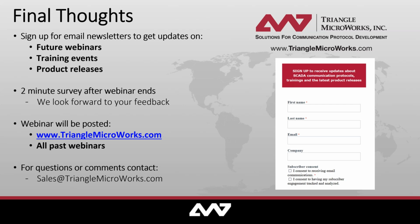Okay, next question. I will just throw out to both of you. Is GOOSE limited to binary values? No, absolutely not. Typically you're not going to have a current or voltage in there, but you can certainly transmit things other than just binary values. The most basic example would be our breaker position, which is just a double bit. So 2 bits side by side that give you the possibility of 4 states: open, closed, intermediate for that fraction of a second while the breaker or switch is neither open nor closed, and then also basically a 4th error condition.